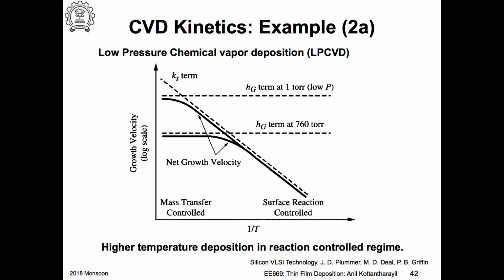So, I can now go to higher temperature, but still operate under the reaction rate limited regime. This is one way to do it. So, reduce the pressure, and I can actually do the reaction at higher temperatures. If I am reducing the pressure, it is usually a low pressure CVD process. On the other hand, if you have high pressure, we are going to bring it down.